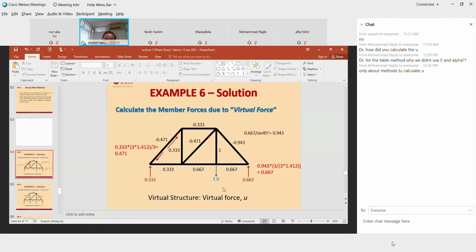This is another thing. When you are doing bending moment and shear force diagram, sometimes we are not encouraged to write one by one, what is RA, what is MA. In certain cases like this, it is very easy and straightforward. This is 1/3, this is 2/3, this is 1/3. Can you understand? Just by ratio.